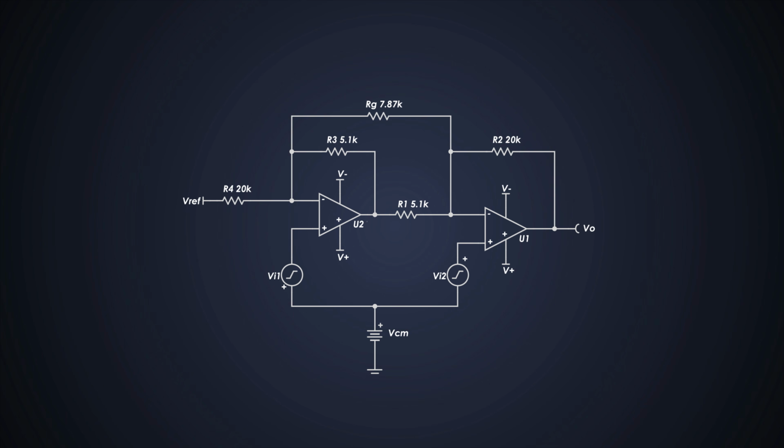This circuit can't operate at unity gain. It has a poor CMRR because of the unequal phase shift in the two inputs, because the signal must travel through amplifier A1 before it is subtracted from Vin2 by the second amplifier. So the voltage at the output of A1 is slightly delayed or phase shifted with respect to V1.